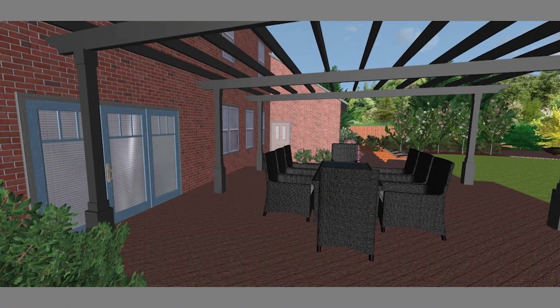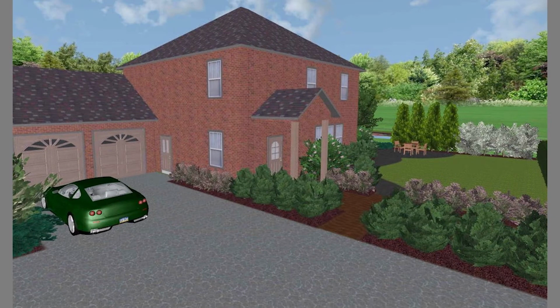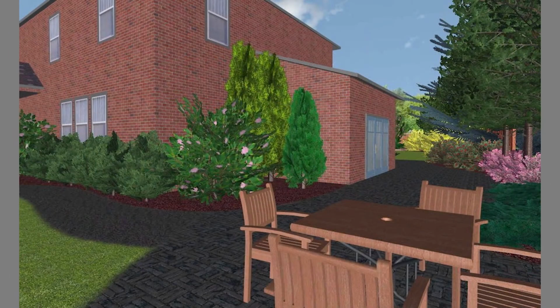The Perspective tab still allows you to edit your design, which is very useful in perfecting the building design, the elevation, and some of the unique 3D functions. The Walkthrough function is the part of the software that allows you to create a hands-free experience of moving through the space, which is useful when presenting the space to a prospective client.